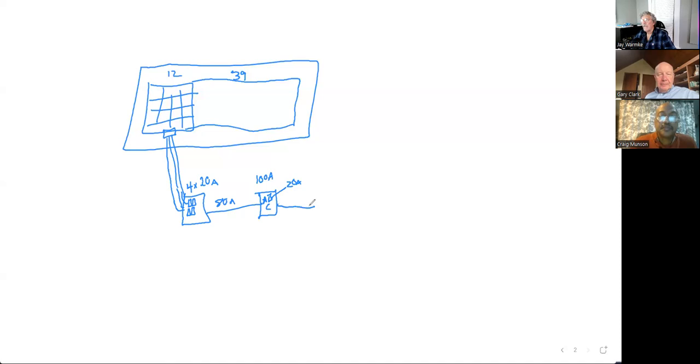Yeah. And then the same thing from here to your service panel. Well, put in 80 amp wire. Right. If you're doing a load side connection, you're going to have to make sure you're aware that this system is probably not going to handle 80 amps unless you swap out the main with a lower breaker. But just pre-wire everything that you can to handle the maximum. So here we're saying, okay, the maximum output of the AC of this combiner box is 80 amps. So let's wire size everything to the maximum.